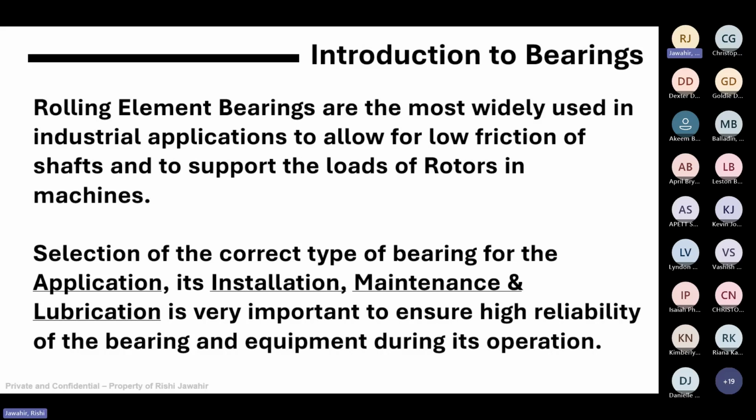From the installation, I think most of us have seen in industry where people use the wrong installation practices. They may pound a bearing into place. They may have the wrong tolerances, the wrong clearances, and that puts undue amount of load or stress onto the bearing, which results in premature failure, which affects our production, which affects our safety.